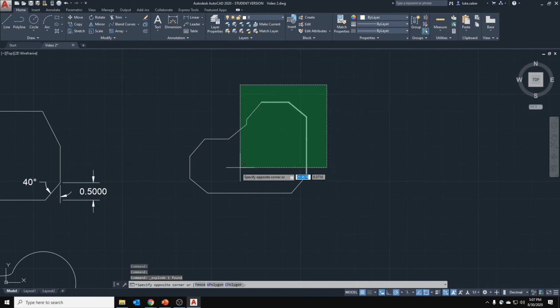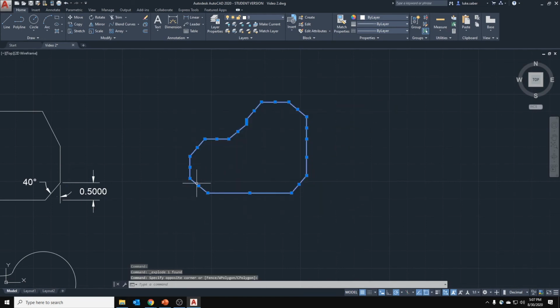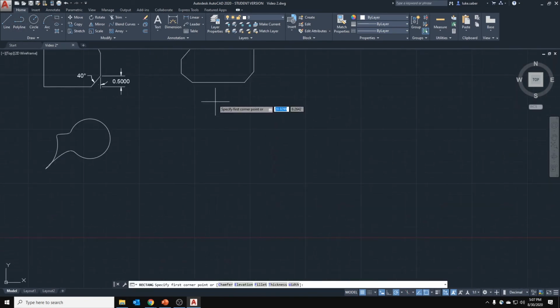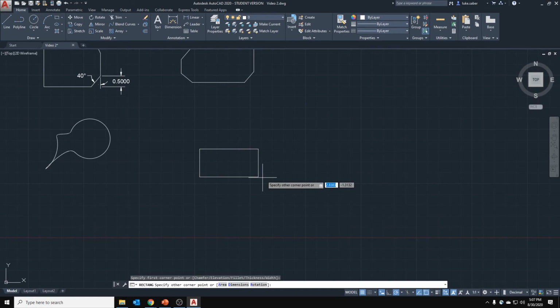And now you can see if I highlight this compared to before, we have so many lines. We have individual segments. They're not a whole line. It's not an entire single unit. It is now multiple units. So we go to modify now, and we'll do stretch. Stretch, what it does is it basically, out of the selected things you have, it'll stretch it away from the rest of the drawing. So a good example of this is that base drawing for this that we had before, right?